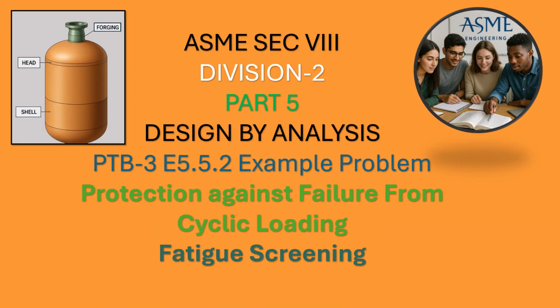This is an excellent example of why screening is only an initial step. It is a quick way to eliminate cases where fatigue analysis is clearly not an issue. But for components like this, we must go deeper. In the next videos, we will do exactly that. We will perform both an elastic fatigue analysis and an elastic plastic fatigue analysis using the PTB-3 example.